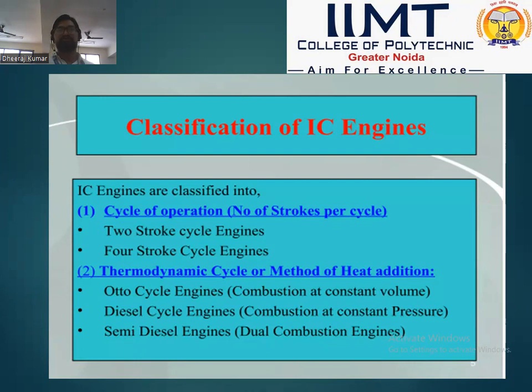Second, thermodynamic cycle or method of heat addition. The engine is classified in three categories: Otto cycle based engine, diesel cycle based engine, and dual cycle based engine. In an Otto cycle based engine, combustion takes place at constant volume. In a diesel cycle, combustion takes place at constant pressure. In a dual cycle engine, first combustion takes place at constant volume and second at constant pressure.